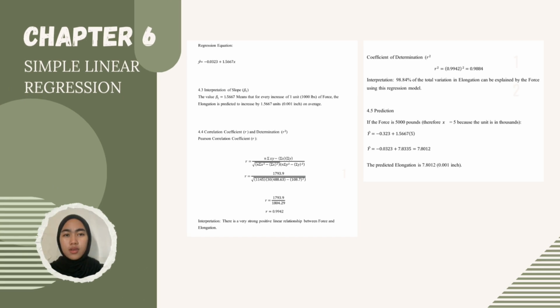Next, the correlation coefficient, R, is 0.9942. This proves there is a very strong positive linear relationship between force and elongation.